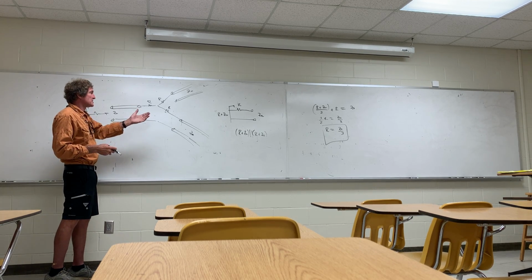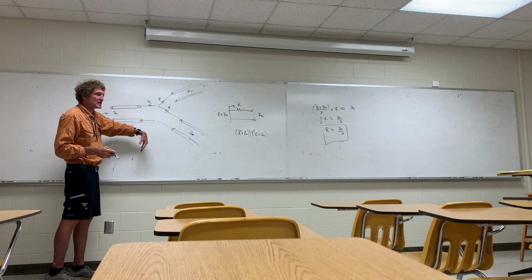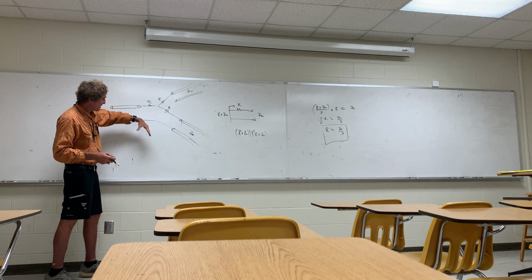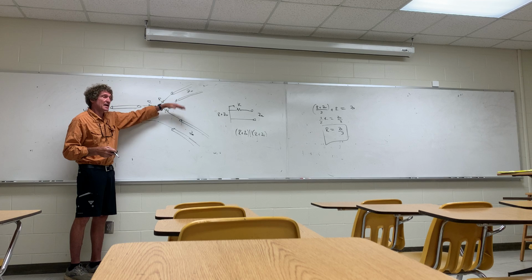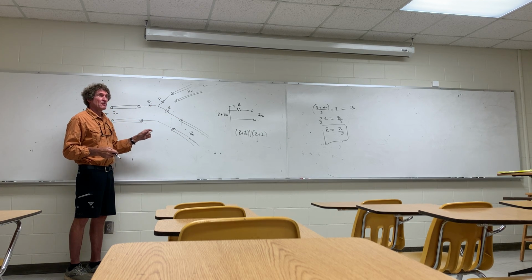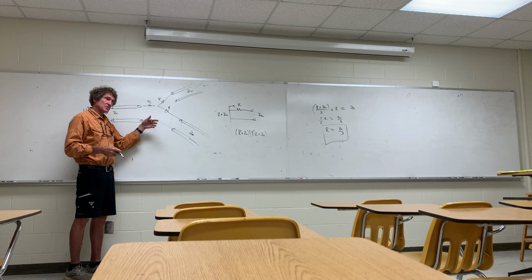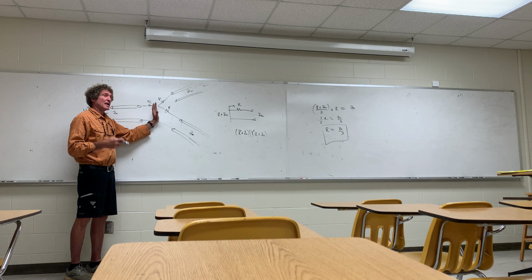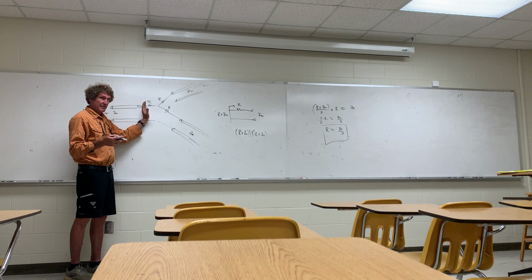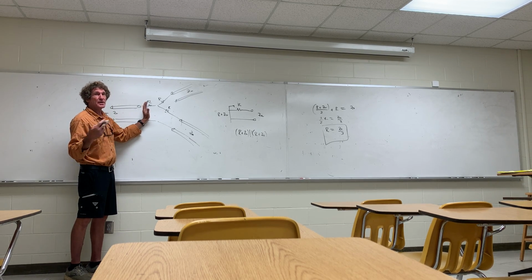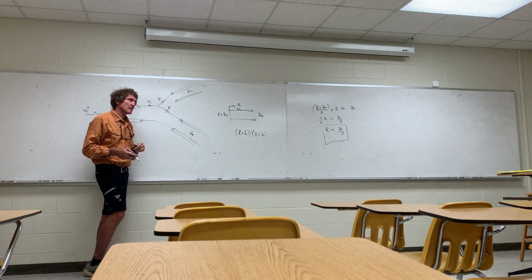What happens if, instead of splitting it 2 ways, I split it 3 ways? Suppose I had another port coming out here, same exact parameters. Then it would be what? At this juncture where the split takes place, I would have R plus Z naught over 3. Y'all follow me? Then you'd have to add R to it right here, and that would be equal to Z naught, and you'd get a different value for R. And it keeps going that way. Can y'all follow the thought process, class? We're going to keep these all the same.